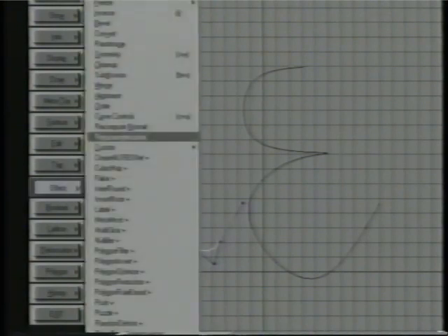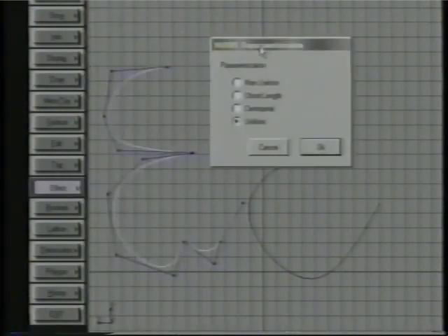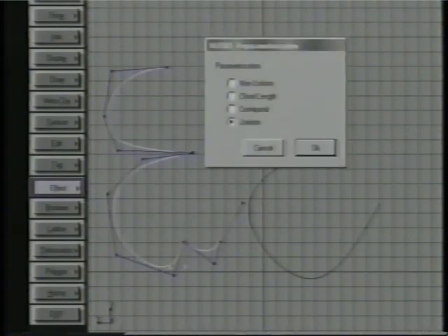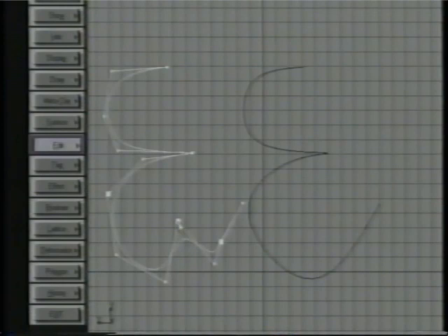Normally, you would use the effect reparameterization feature when you're dealing with surfaces, but you can also use it on curves. So for instance, here we've made that hard edge. Well, those are actually the knots that are all put in that same place to make that hard edge. So you have the knot from this point here, from this point here, and from this point here. They're all stuck in that same place. You can't actually see the knots, but you can reparameterize, and you can see how that changes. So now we have the control in this region, and that region. Whereas before, this is more like a handle.